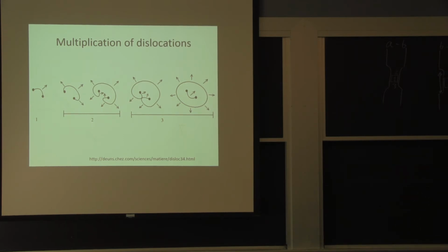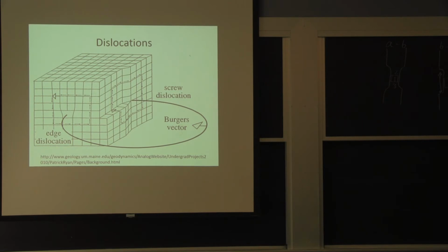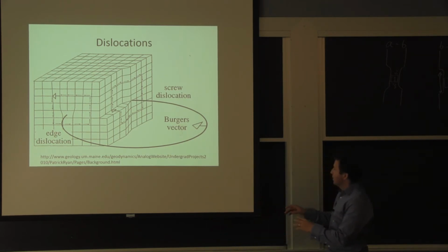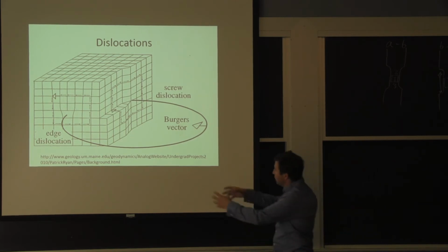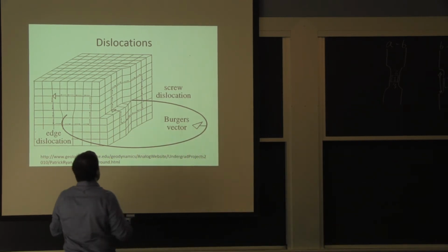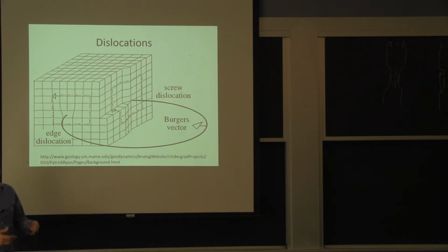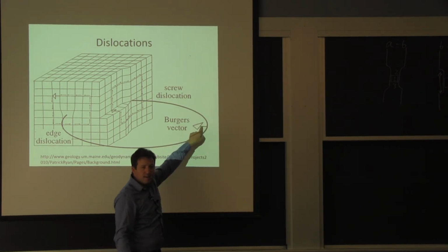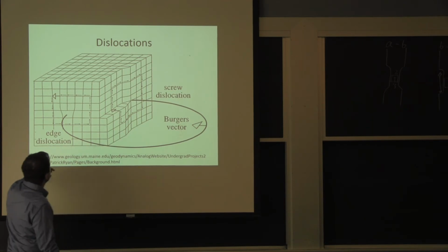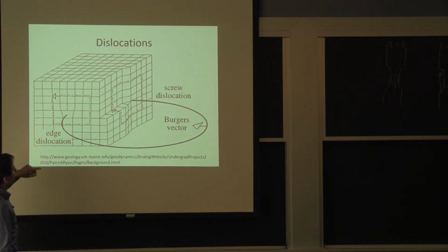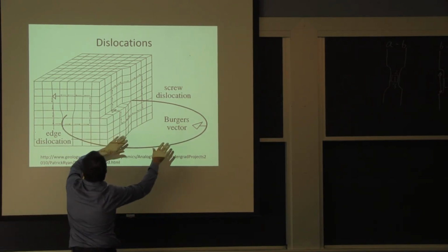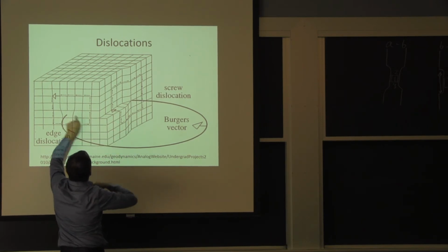Okay. All right. Now, I took a little bit of time to select this one image. This is as deep as we're going to go in terms of dislocations. This is about 1/8 of a full 3D cube where we essentially create a dislocation loop out of nothing. You see the dislocation Burgers vector here. This indicates the direction of the movement of the atoms. Essentially, if I take everything on that plane, on that circle, and I just move it a little bit, that's what I'm getting.